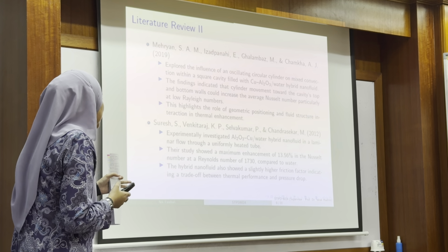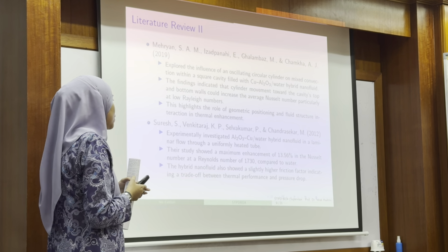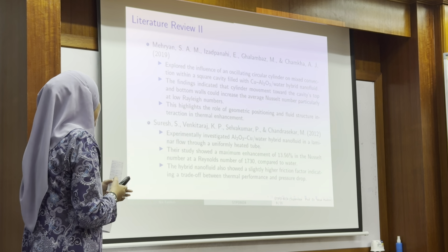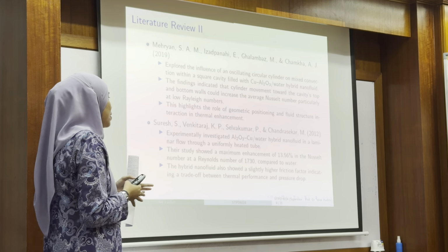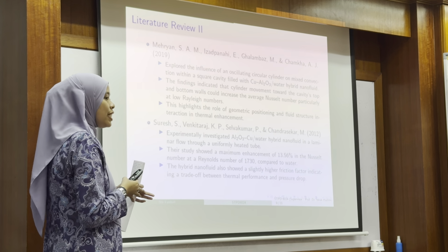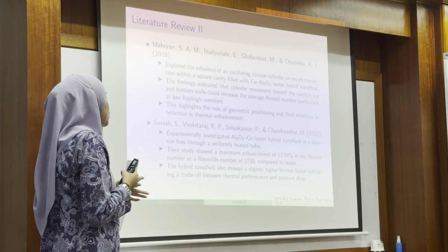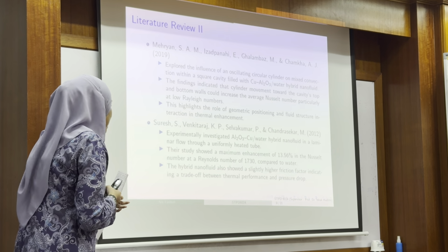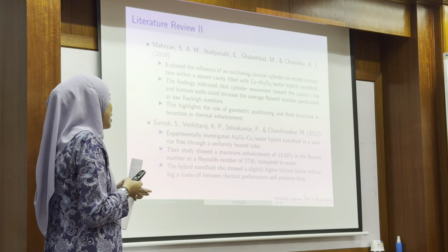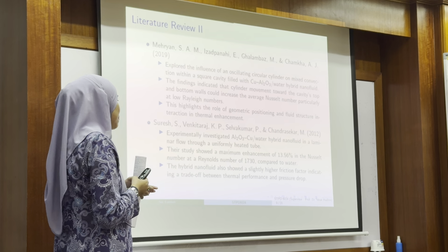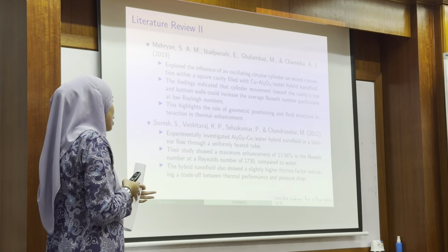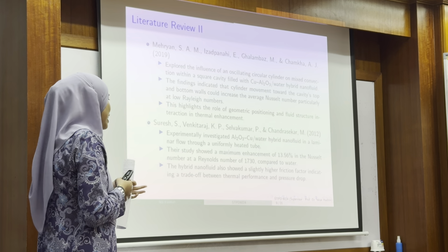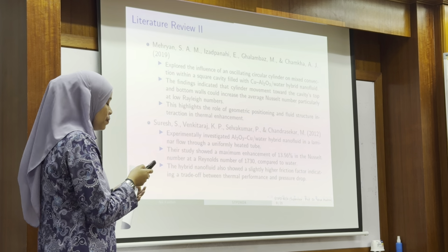So the last literature review is from Suresh et al., 2012. They did an experiment to investigate the aluminium oxide water hybrid nanofluid in a laminar flow through a uniformly heated tube. Their study showed a maximum enhancement of 13.56% in the Nusselt number at a Reynolds number of 1730 compared to water.